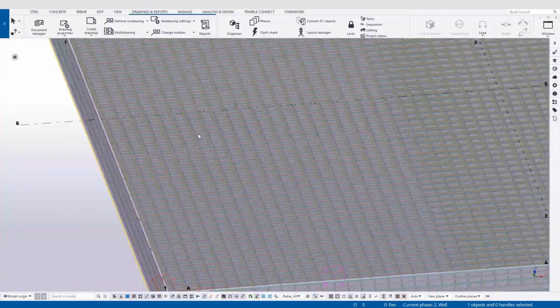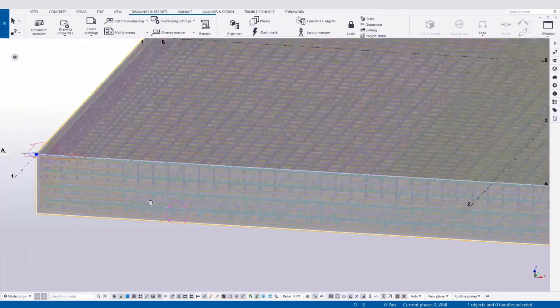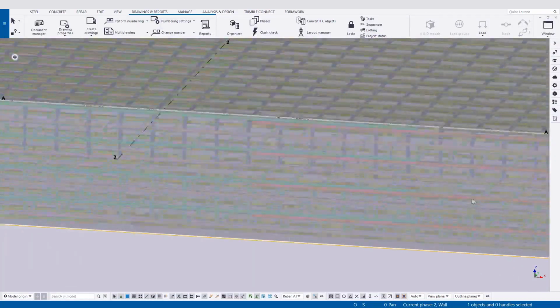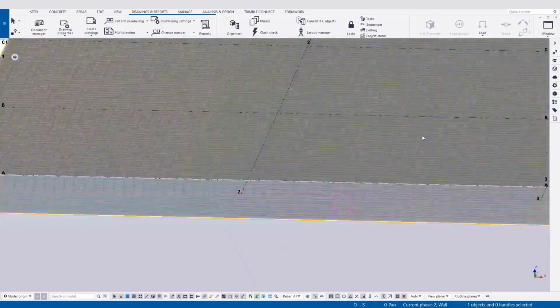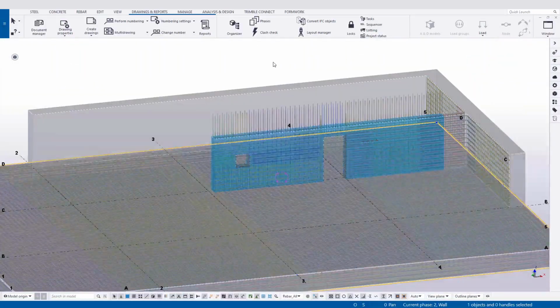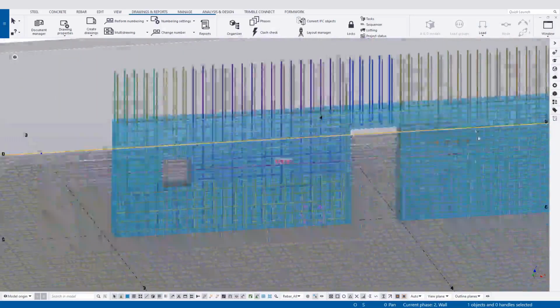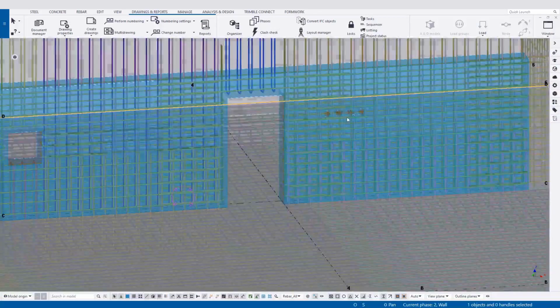We're doing splices, no mechanical connections. We have edge bar with staggered splicing as well over here on the edge. And then we have one portion of a wall that's detailed fully and attached to some other concrete. We can see here we have splice dials coming up from the base mat, and we'll have some additional reinforcement and some openings and blockouts.